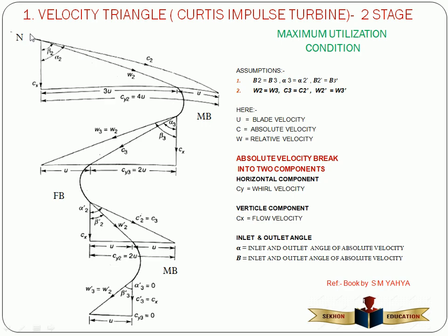That is the nozzle here. That means we get a velocity triangle which does not have any relative velocity component, because the nozzle is the fixed part. The velocity of the jet of steam which leaves the nozzle, the absolute velocity, increases tremendously because it converts the pressure energy into kinetic energy.